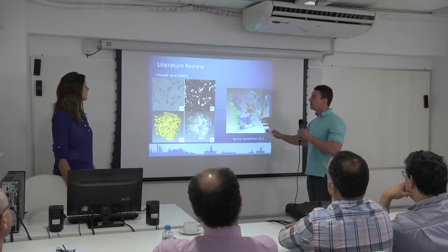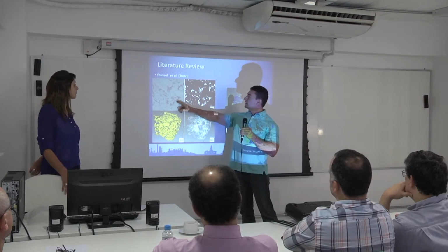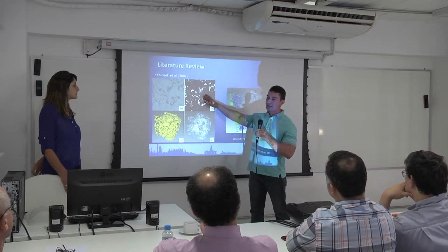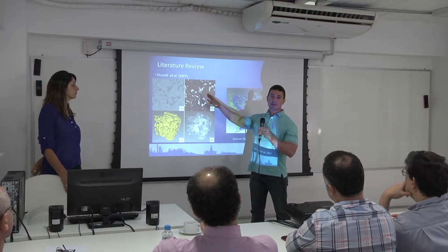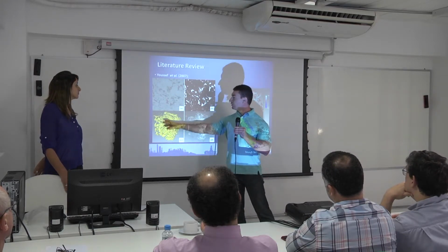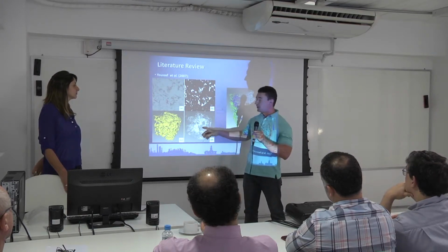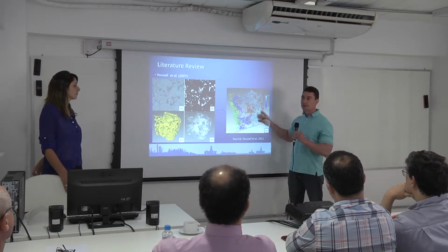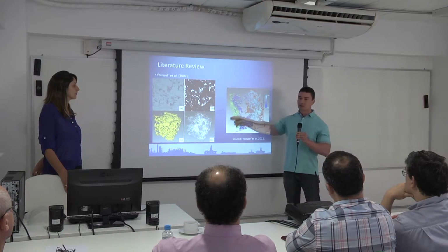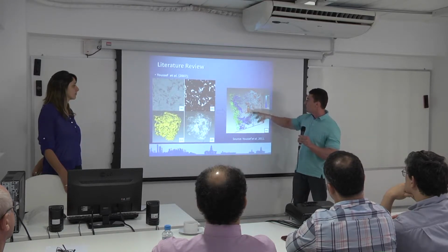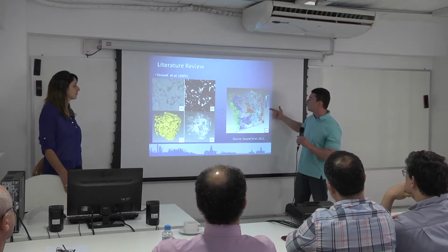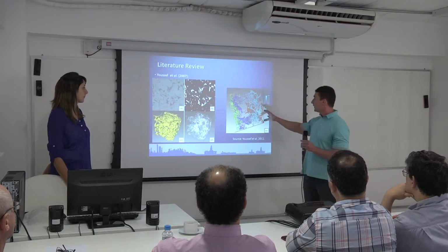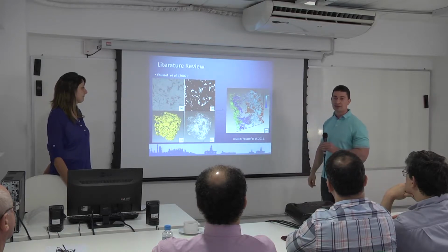And here, just to describe a little bit of their work, they made the 3D images through the micro-CT. They used black and white to binarize the image. They reconstructed the pores, and then they extracted the connections of these pores, and then they simulated a pressure gradient. This is the inlet and here the outlet of this sample. You can see that you have a pressure gradient here from 2 bar to 1 bar. It's very interesting because it's the first time that we saw them creating a pressure gradient in their work.